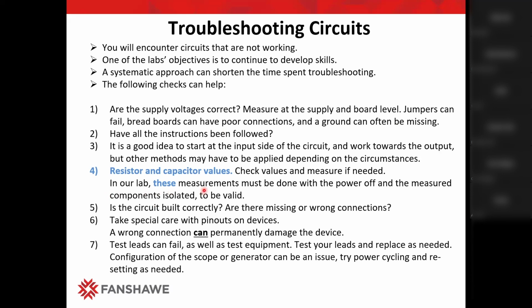In our lab, these measurements must be done with the power off. This is what we teach in most of our courses. If you want to check the resistance of a resistor, you have to take the resistor out of circuit, and one of the ways is to lift one leg. If you lift one leg of the resistor, that whole resistor is out of circuit. Then you can measure the resistance.